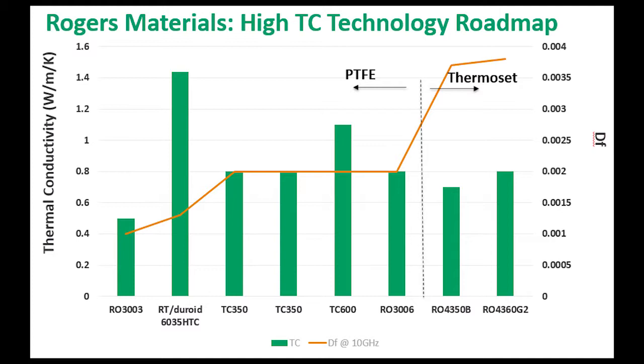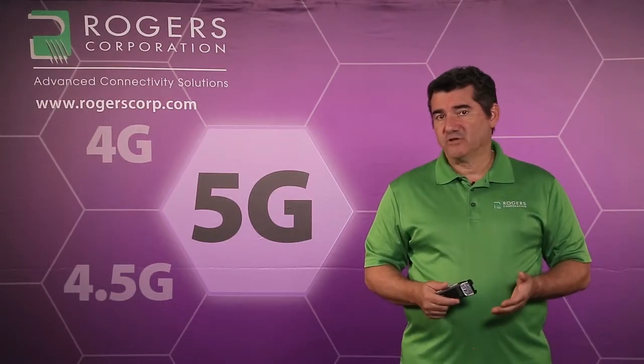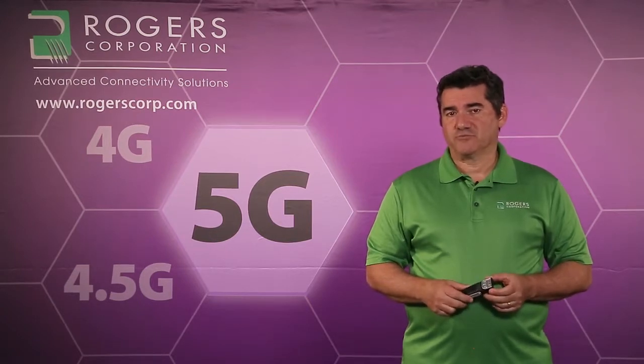When we look at the thermoset materials, we have valued materials with loss tangents of 0.004. That's what the yellow line shows, the values of the loss tangents, and thermal conductivities in the area of 0.6 to 0.7. So these are the various choices that we have, either in high dielectric constant like the 4360G2, TC350 and the RO3006, versus those with the lower dielectric constant. These are the materials we have to choose from when selecting materials for high power applications and thermal management. In addition to material properties like loss tangent and thermal conductivity, what else should a designer be looking at when selecting the right material for thermal management?